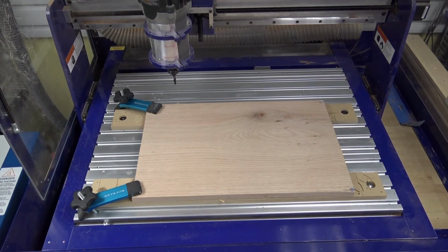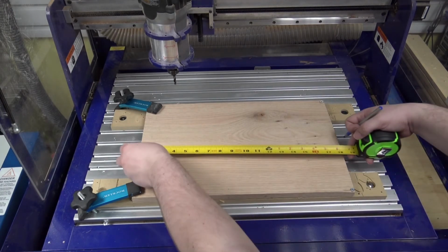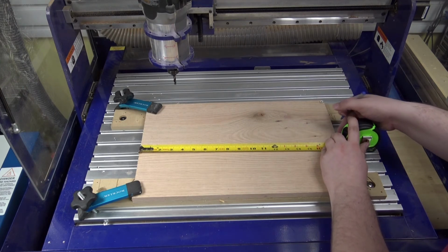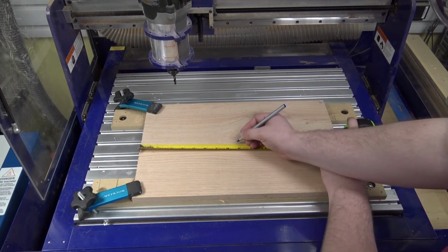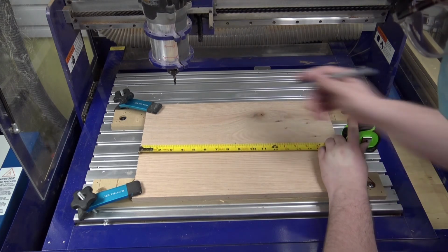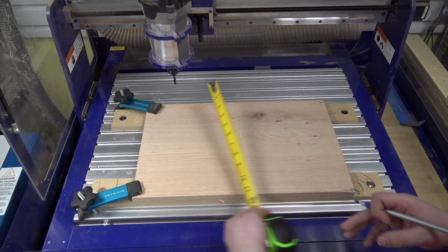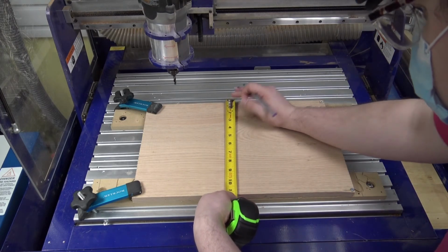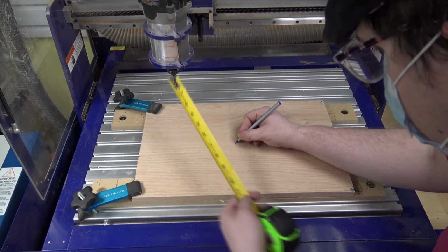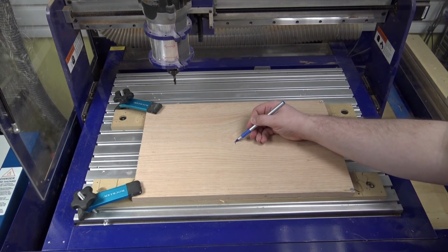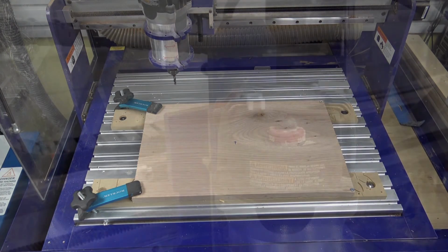Now we will find our home position. On this job, we use the center of our material as the home position, so we will measure it out and mark the central location as accurately as we can. At times like these, it's important to remember the old woodworker saying, "Measure twice, cut once." This central location will be where we are moving to in the next step.